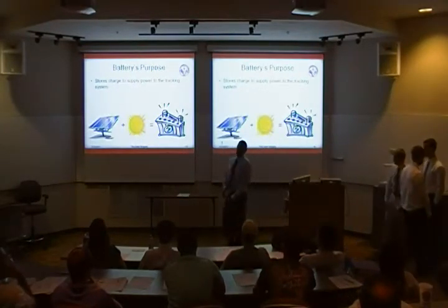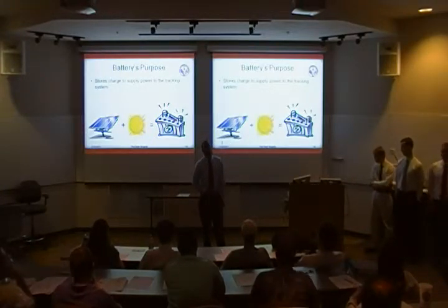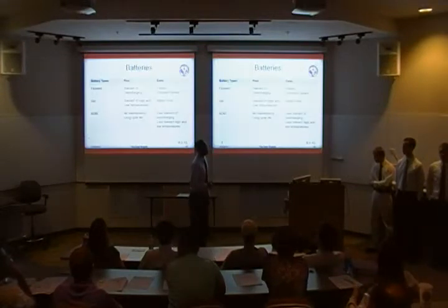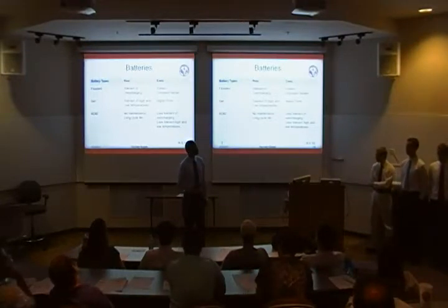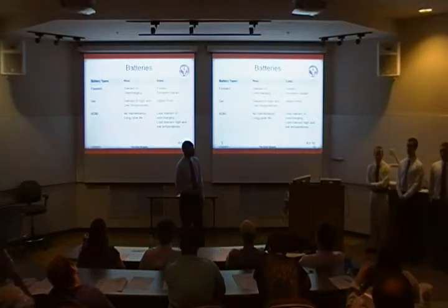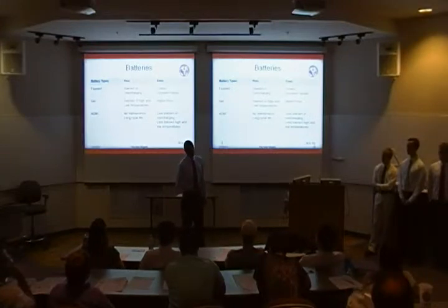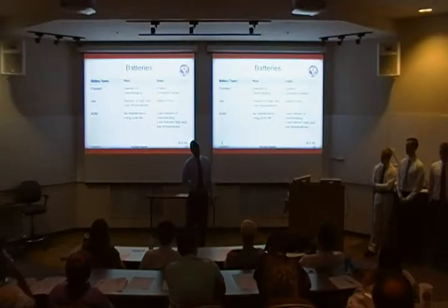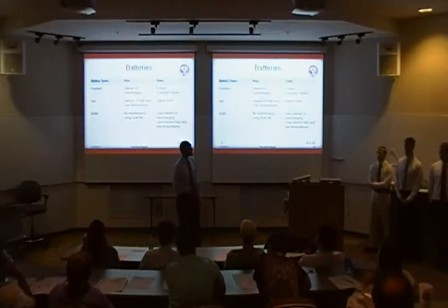The battery we use will be a rechargeable battery that will receive constant charge from the solar panel and we use this charge to power our circuit. There are 3 types of batteries we researched when considering which one best suits our circuit's needs. We have the flooded battery, the gel battery, and the absorbed glass mat battery, also known as the AGM battery. A major con we noticed about the flooded battery is that it disperses fumes which can become a corrosion hazard to our circuit. This is economically a disadvantage to us because corrosion damage costs us time as well as money to find replacement parts for our circuit.